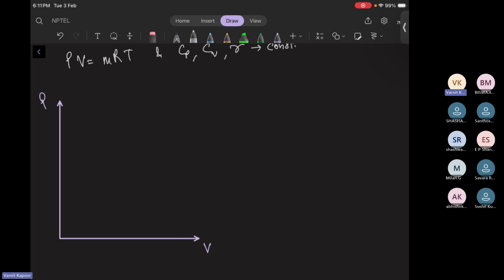One of the basic cycles of a petrol engine, we are starting with the Otto cycle. We will come to the real cycles as well in the later part of the course, don't worry about that. But first we have to develop the basic understanding of how the cycle works. The first one is the compression process. We have assumed that the suction has already happened, and when we are compressing, the pressure will rise and the volume will decrease.